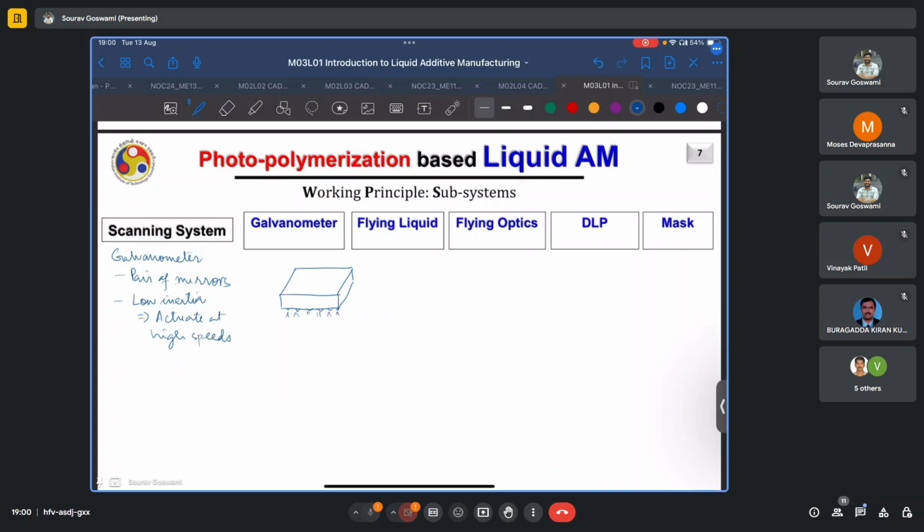And depending on, say, the area of the layer to be deposited, the area of this deposition head, the nozzles, and the pixel resolution, the head will move a finite number of times over each area. Say, if we are looking at the top view, this is the area of the total region of interest over which my structure is to be deposited, and my head is this big, then it will cover this region at once, depositing material at all these points.